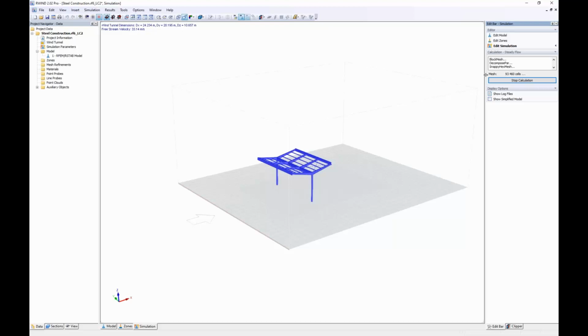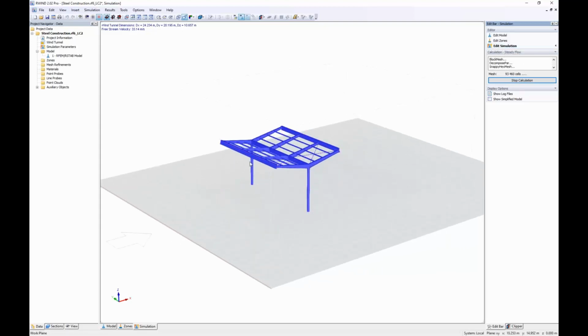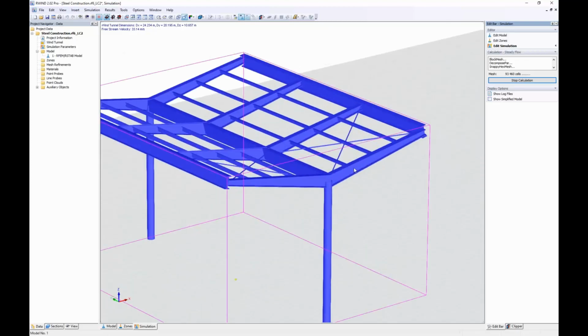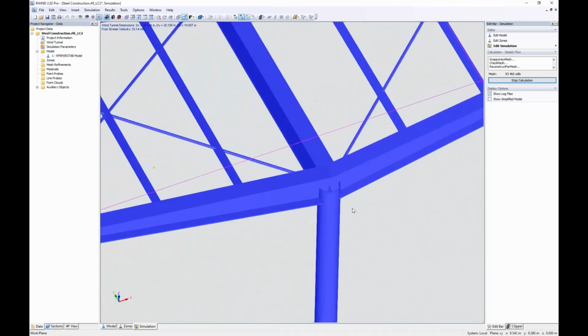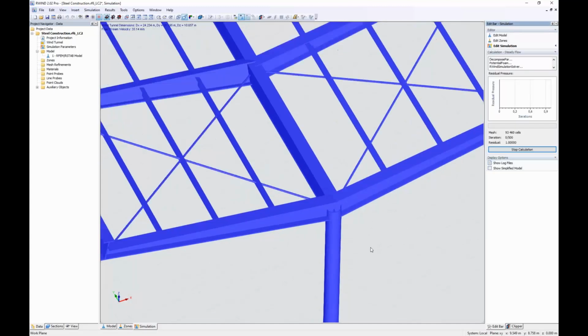And then the process is running down all these steps, what means he creates a shrink wrapping mesh around this sharp-edged model from RFEM. This is maybe we call this a simplification step, and we do this to make it wind-proof. What means if you see such things here, this coming from this rough modeling of a structural model, but we don't want that the wind should go inside, so we make it windproof, we bind a foil around.